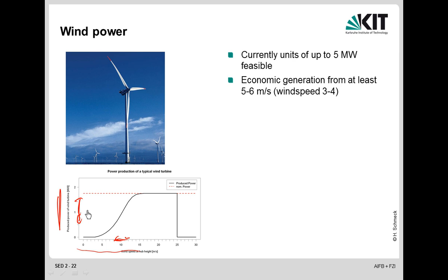And it means that you have quite some fluctuations in power generation from wind. Because it is this area where it is just a very steep slope here. And small changes in the wind result in dramatic changes in the power that is generated, and so we have this very fluctuating character of power generation from wind. One could try to compensate that by using large batteries. In some countries, they are always building a large battery pack beside those wind power plants, and then they can provide stable power from the battery pack. But this is extra investment, makes the power more expensive.